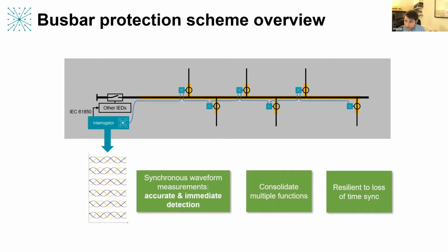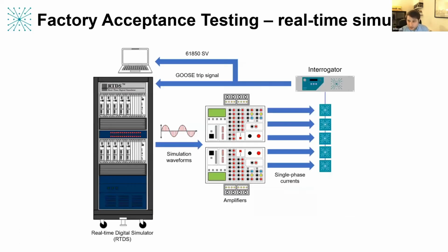And although we do normally provide PTP-based time synchronization to provide a global time synchronization reference, even if we lose that source, if the clock is offline or some other issue, we still provide relative synchronization of all the measurements. So we're very resilient to external failures in the system. We can still provide the protection functionality or other functionality that's needed.